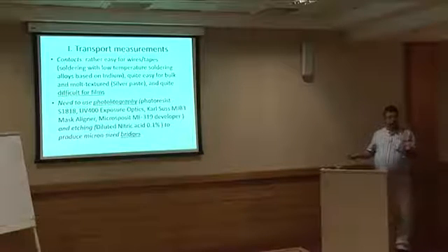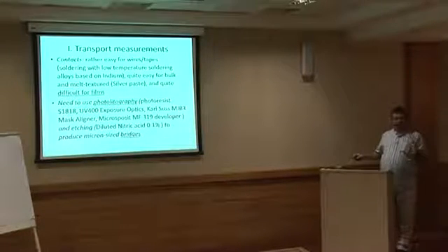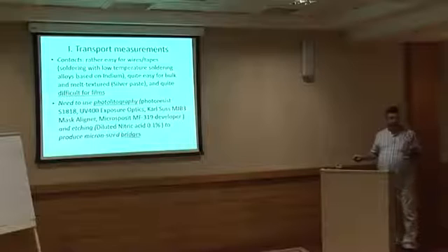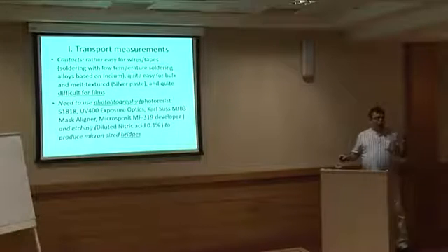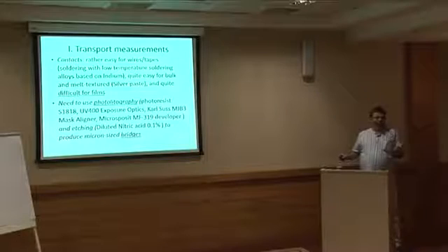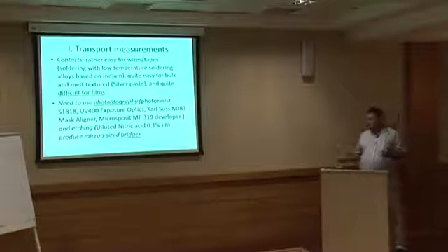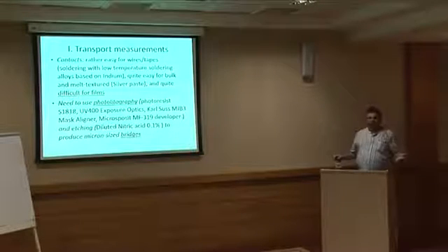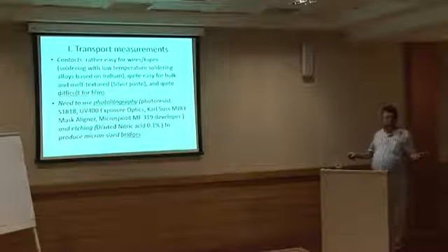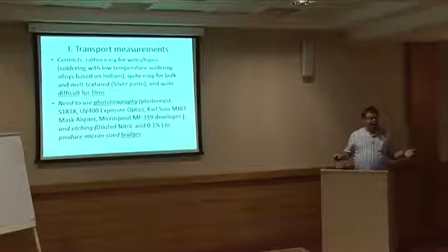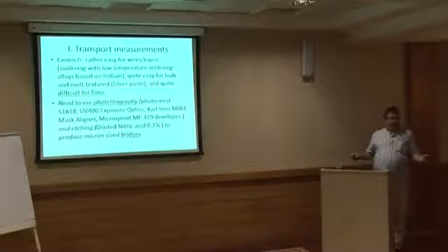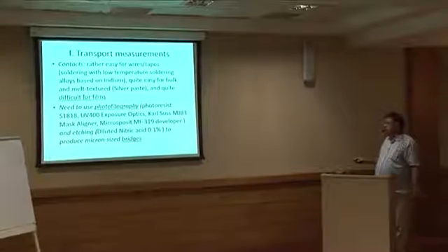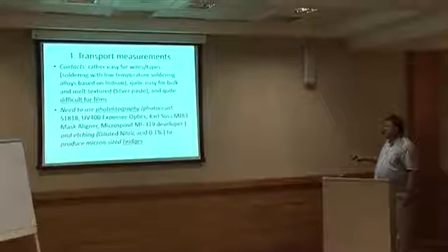bridges which have not very high cross-section, because with a large cross-section and the huge critical current densities we have, it means we need to put a huge current inside. First of all, usually not everybody has such current sources to put in 100 amps or something. Second, you will use a lot of power in your lab. And third, you might very easily fry the contacts because you lose a lot of energy at the contacts, and also thin wires have problems. So that's why we need to produce micron size bridges.